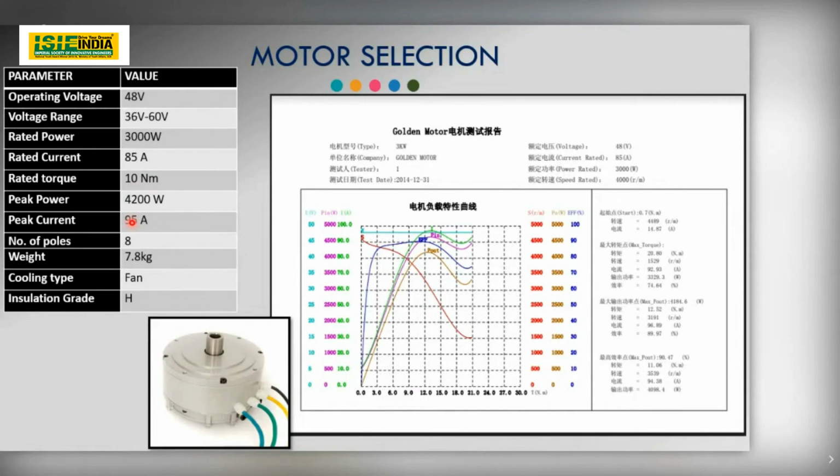Peak torque is required by the transmission system to take the vehicle from a steady state to a dynamic state, and rated torque is the nominal torque that the motor provides for the entire duration. These are the filters that we use for selecting a motor.